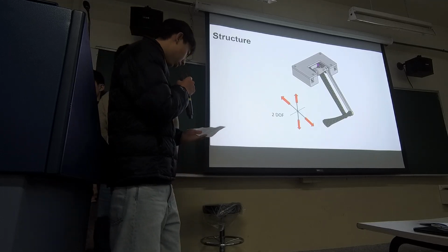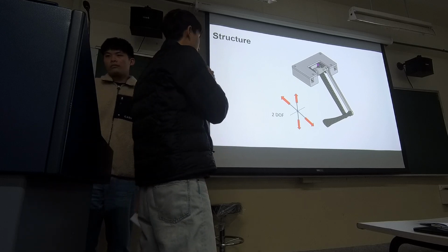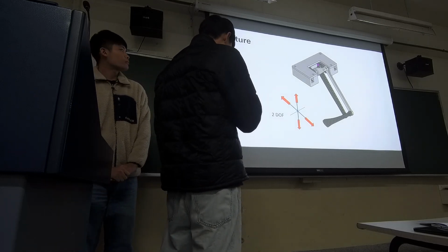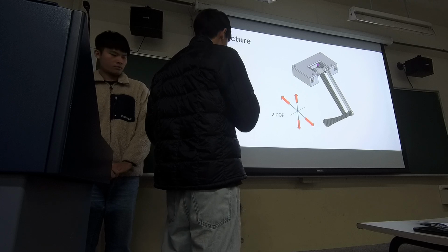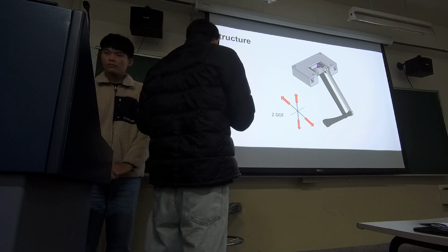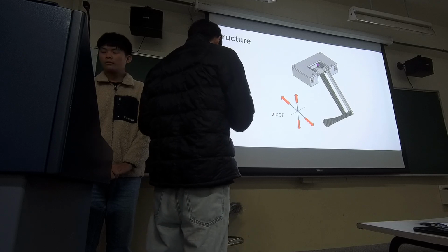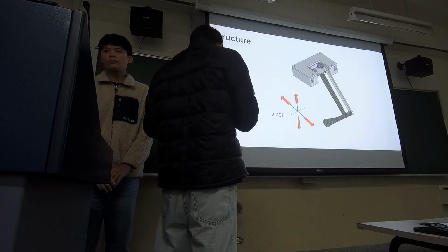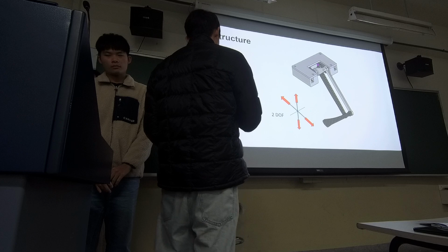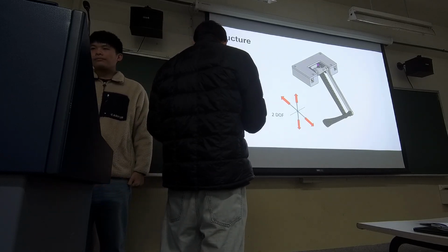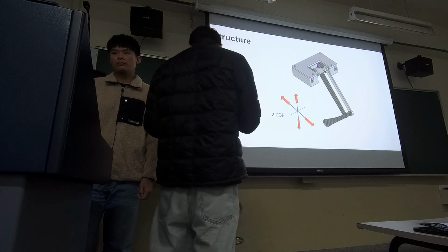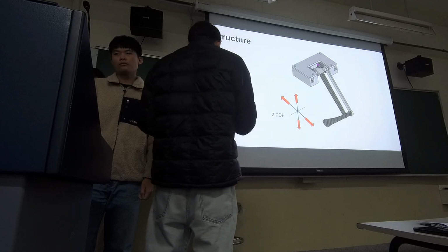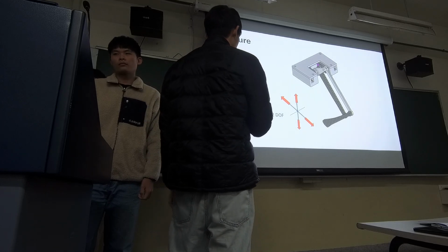We designed a single structure in the office. We prefer the Stanford open source Pupper structure. We made modifications to the design to suit our specific requirements, and control the servo at different angles to achieve 2 degrees of freedom: forward and back, and up and down.